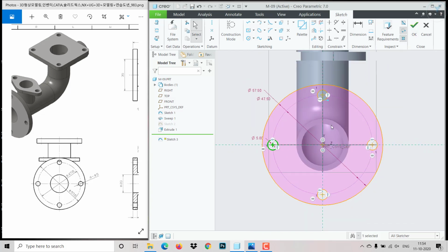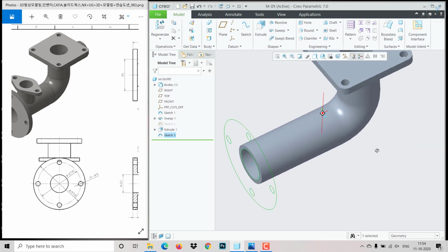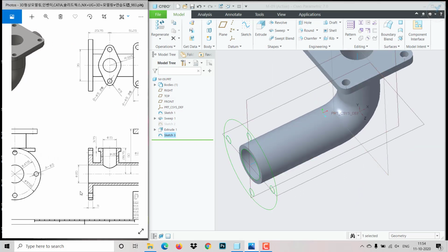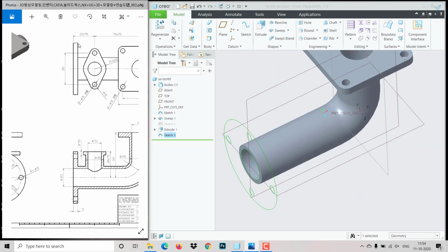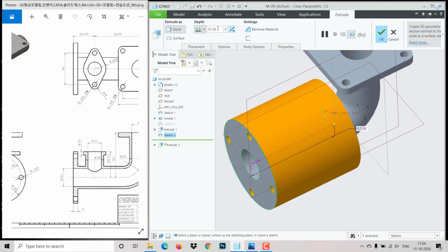So we need to do the same thing here also. We need to make it hollow. So click on project, either outer or inner. We can just project one, then click OK. So this one has a thickness. Consider it has to come inside. So click on extrude, flip the direction, with a distance of 5 mm.